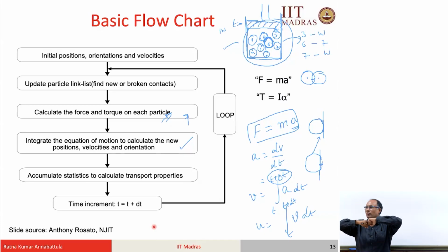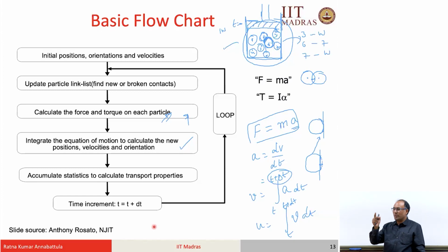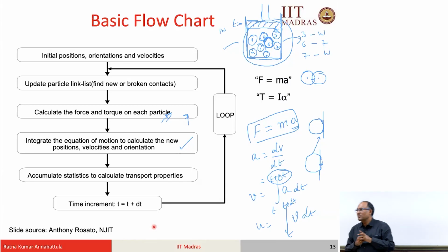We will see what kind of constitutive relations do that, for example, the Hertz-Mindlin contact law. That is why the contact constitutive relation is very important, in how it enables that. Here I am explaining the algorithm right now, but there are two approaches for DEM simulations that we will talk about. Whatever I am talking about right now is called the soft sphere approach, wherein the particles are considered deformable, but we will not model the deformation.